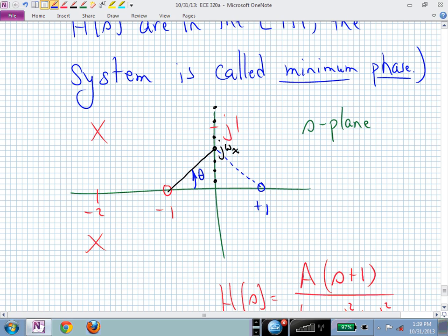But the angle of this 0 in the right half plane, even though that 0 produces exactly the same magnitude behavior, what happens to its phase? Measured from the positive real line emanating from that singularity, that phase is not minimum, is it, for the same magnitude? That's why we call them minimum phase systems if our zeros are in the left half plane.